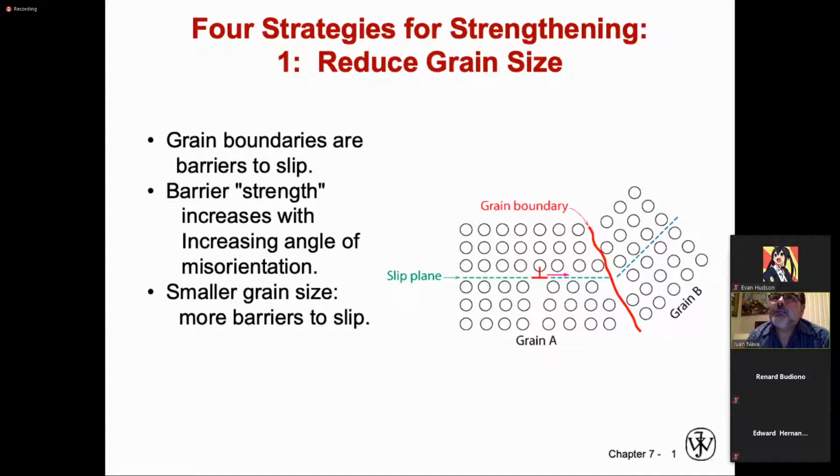You know that the grains that are closer to the mold material where the liquid is solidifying will form with a finer grain structure than the ones that are forming from the inside of the molten pool, because there is a larger path for the heat transfer. So heat is withdrawn slower from the center of the mold toward the edge of the mold. That will define whether you have a fine grain or a large grain structure, which is critical in order to define which one, the fine or the large grain, is the stronger.